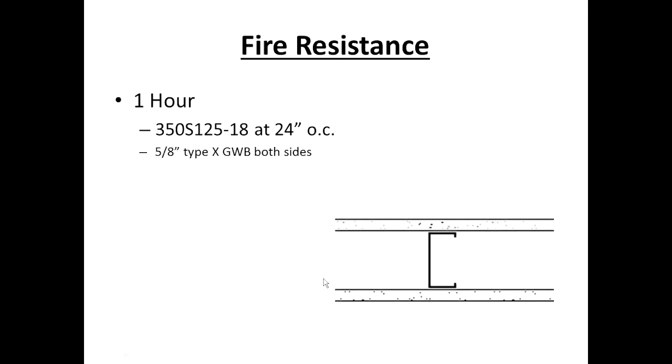We're going to start to build a wall. Metal stud construction, 18 mil, 24 inches on center. We've got a 3 5/8 drywall stud, a 1.25 flange, a layer of 5/8 Type X board on both sides. A little sidebar here when it comes to gypsum panels, and we're talking about fire ratings.